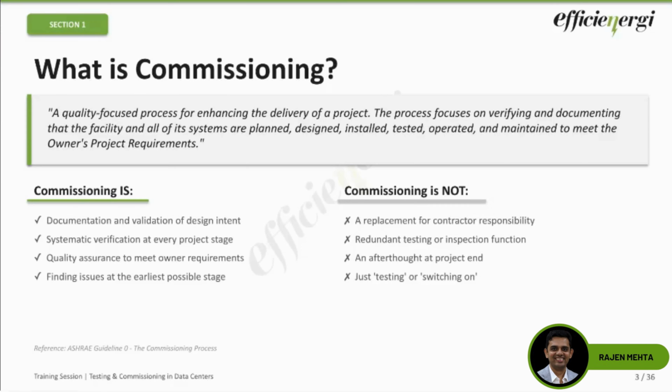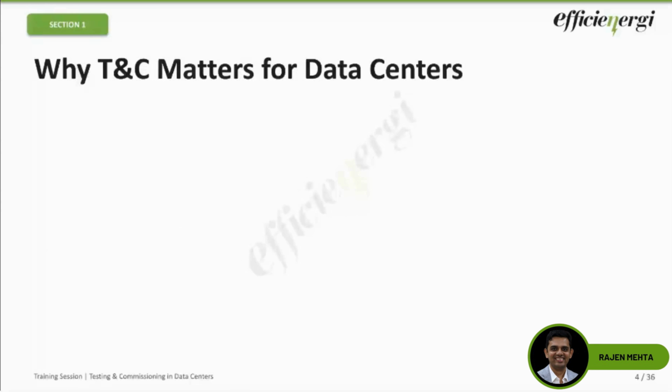Third, it's not something that you add at the end. It is not that we just energize it and call that commissioning. That's not how it is. It is supposed to start at the design stage itself. And last and most importantly, as I said earlier, it is not just switching on. Commissioning doesn't talk about just switching on. That's a very small fraction of what commissioning comprises. Okay, so those are the key things I want you to remember from the previous slide.